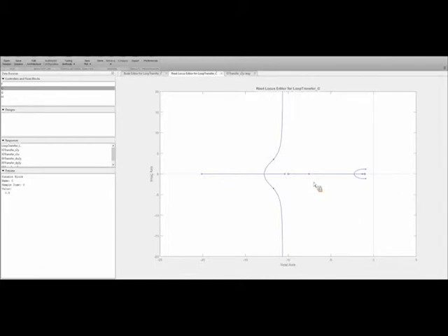I think it is, and if you look at root locus, that's usually how we introduce this idea to undergrads first learning this, because it works for fairly simple systems. This is fourth order, so now we're pushing the limits of how much good information you can get out of this. We'll be getting into frequency domain tools, which are usually used for more complex systems, because it's not so wishy-washy in terms of how you read these. But here we would say that we have a pole here as well that's going to have an influence, where before it was canceled. I don't know if that helps.